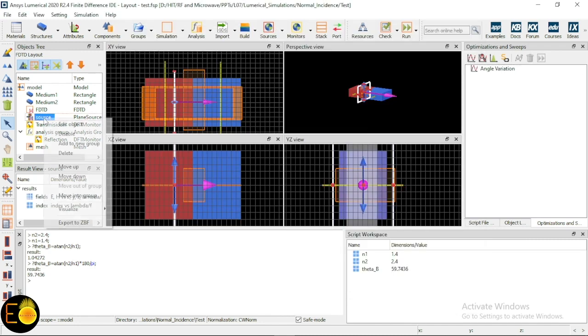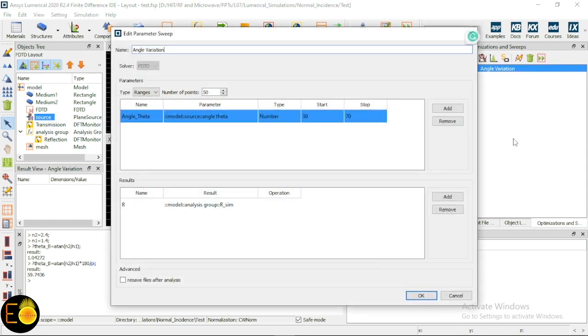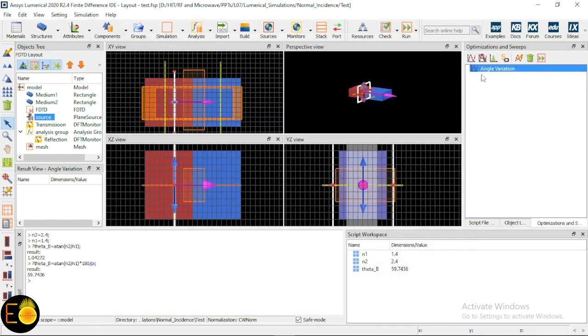The source angle I set to 90 degrees, so by default, it will be TE polarization. Now I am interested in recording all the data for TE and TM both simultaneously, and that will be done automatically by sweeping the parameter. Therefore, I need to initiate another parameter sweep, and that parameter sweep will be for TE and TM. So I have to right click on that angle variation and insert parameter sweep. This parameter sweep is coming above this angle variation. Now rename it as polarization sweep.